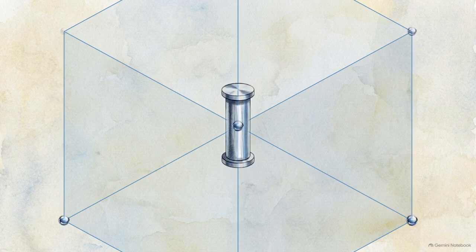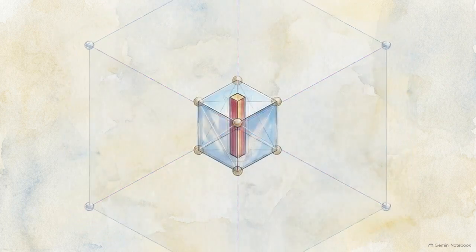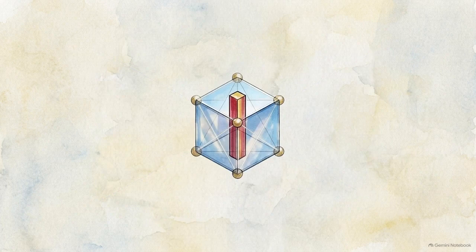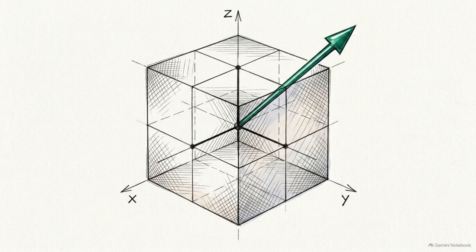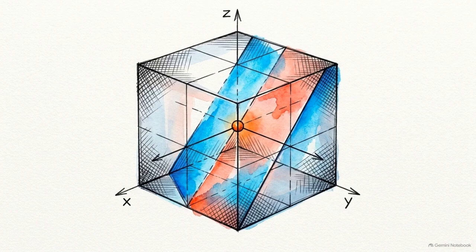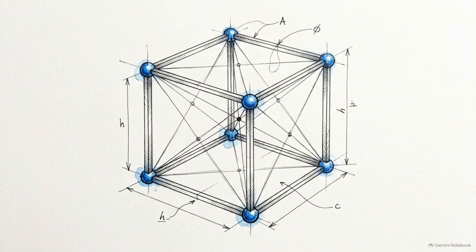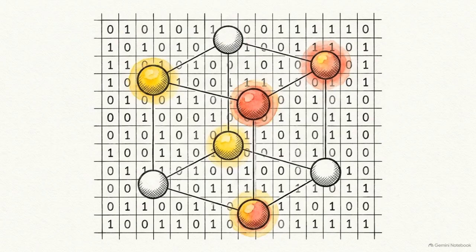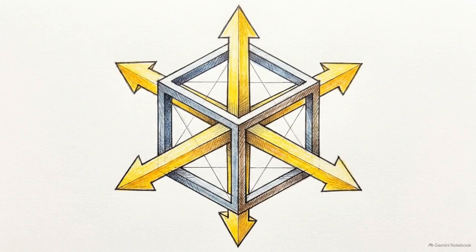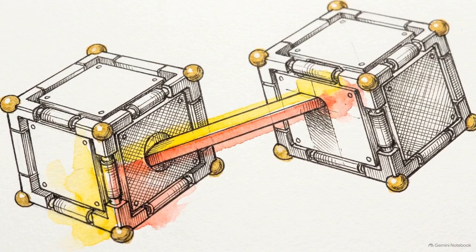Inside a single active voxel, the system relies on a structure similar to a tent pole and surrounding pegs, a center support combined with tension points to hold the geometry taut. The pole is the primal anchor. It is a single plotted point containing absolute position and normal data, representing the primary intersection of the surface within that specific voxel. The pegs are the dual anchors. These provide up to 8 additional positions and normals, equipped with a mask to map the topological context directly surrounding the primal point. Finally, the system registers the semi-axis orientations, 6 directional flags along the X, Y, and Z axes that dictate the precise connectivity between the primal anchor and its neighboring voxels.